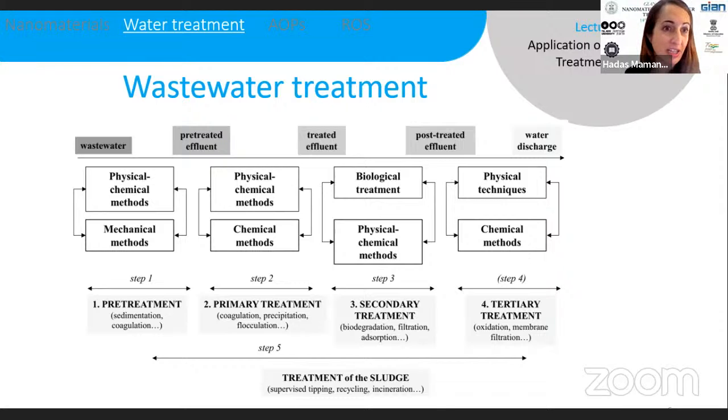Since the advanced oxidation increases the biodegradability, the effluent then undergoes biological treatment. So there are many places where AOP could be implemented. There's also a study that used, for example, ozonation on the raw sewage to enhance coagulation and also oxidation, but that is more rare and mostly for industrial-based wastewater.